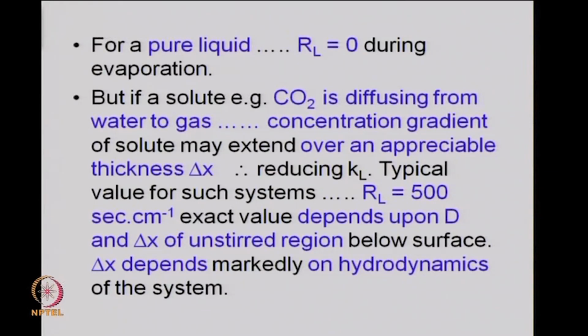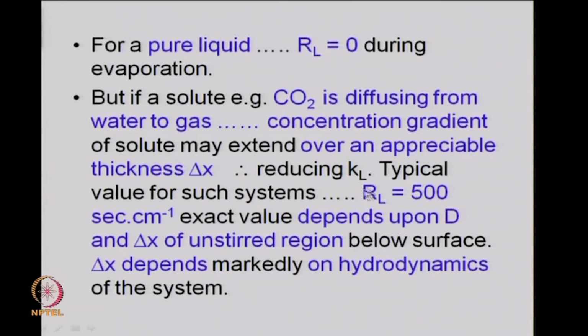This is true for CO2 either diffusing from aqueous solution into air or the other way around. And if that resistance is to be characterized by the thickness of the liquid which is involved, then obviously the liquid phase resistance would be quite high. In such a case RL is as high as about 500 seconds per centimeter.